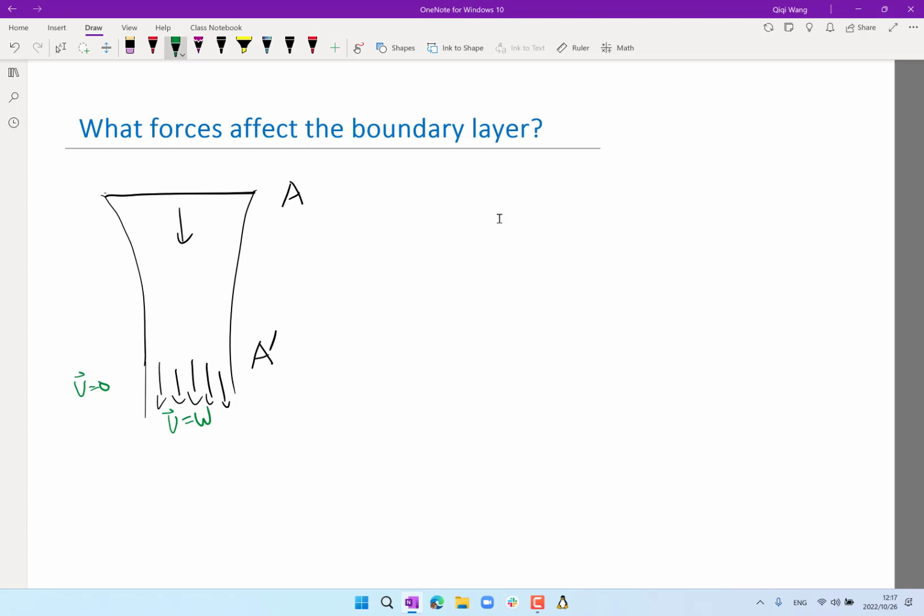Second way to think about it is that in potential flow, we said that we can also apply Bernoulli across streamlines if the vorticity is 0. Here, where has non-zero vorticity? Where is vorticity non-zero in this flow field?